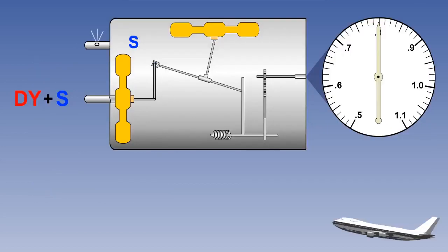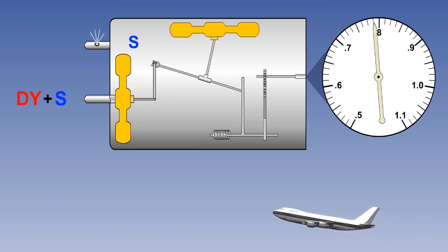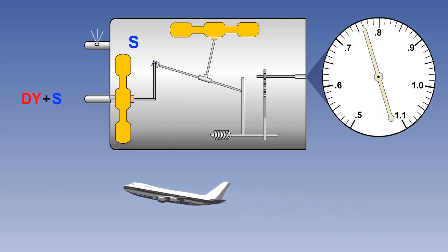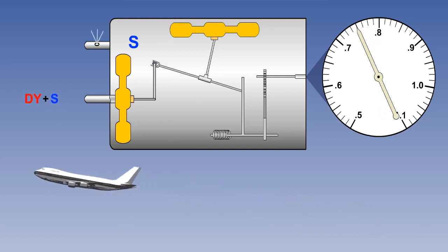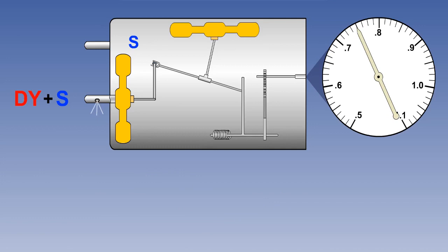A leak in the static source within the pressure hull will cause the pressure sensed to be the same as the pressurized hull, and the Machmeter will underread in the climb. If a leak develops in the pitot source, the pitot pressure will be low, the airspeed capsule will not expand correctly, and the Machmeter will underread. This concludes the lesson. A brief summary follows.